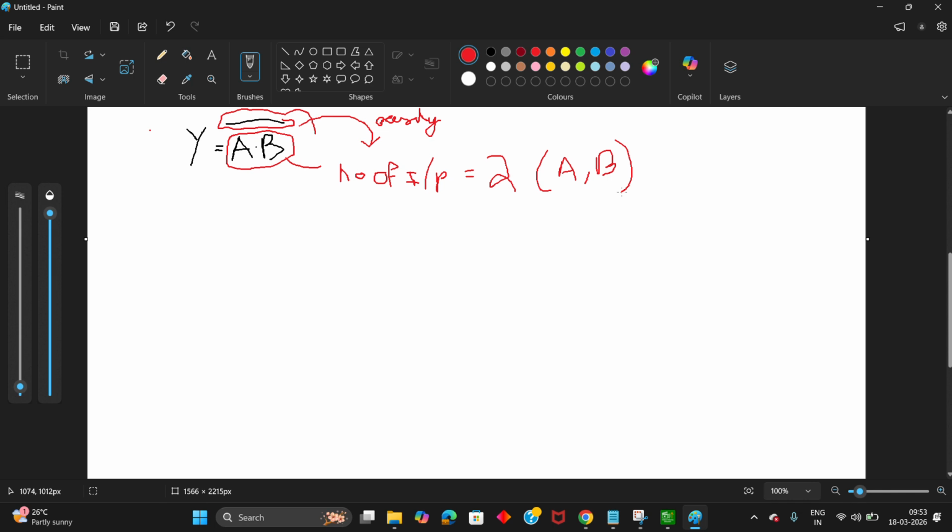So your number of PMOS and NMOS transistors will be equal to the number of inputs. Okay, this is the point you need to remember. The number of PMOS transistors in the pull-up network, right? I already told you why the pull-up network is called pull-up and why pull-down is called pull-down in the NOT gate discussion. You just watch that video.